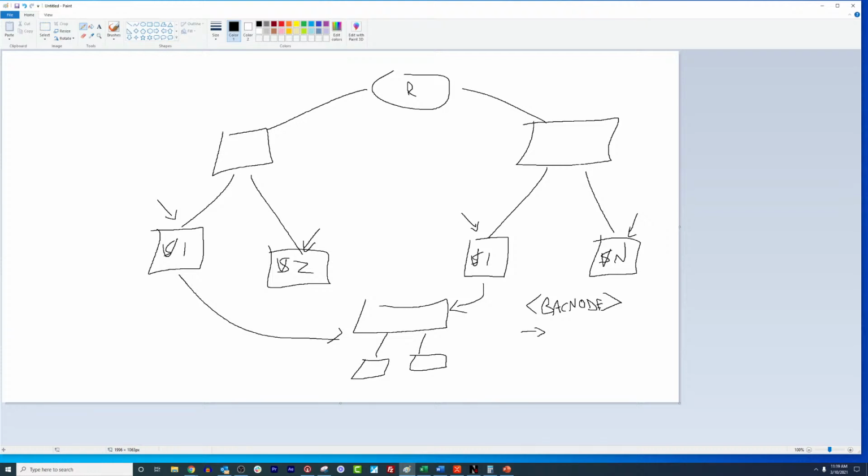I work for a campus where we have over 200 BBMDs and we're trying to reduce the number. We're fighting with IT to get us a VLAN set up. Yeah, that should be a significant reduction once you get that VLAN set up, because broadcasts cannot traverse IP boundaries. So they cannot traverse subnet boundaries.